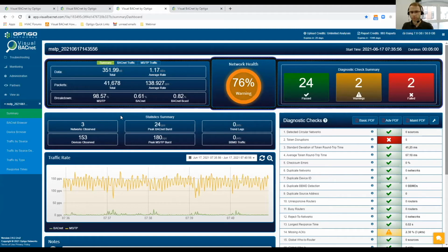Yeah, for sure. Because you were already capturing and already on the network, it should be as simple as unscrewing one of the wires, hitting the next capture, analyzing it instantly, and moving on to the next step. Yep, that's it. Just split the network wherever we chose to, drop out the outgoing connection to devices downstream, go into the web browser of the capture tool, drop it down to its minimum time, just start it, let it go for 5 minutes, wait for the file to upload, and see what results we get back.